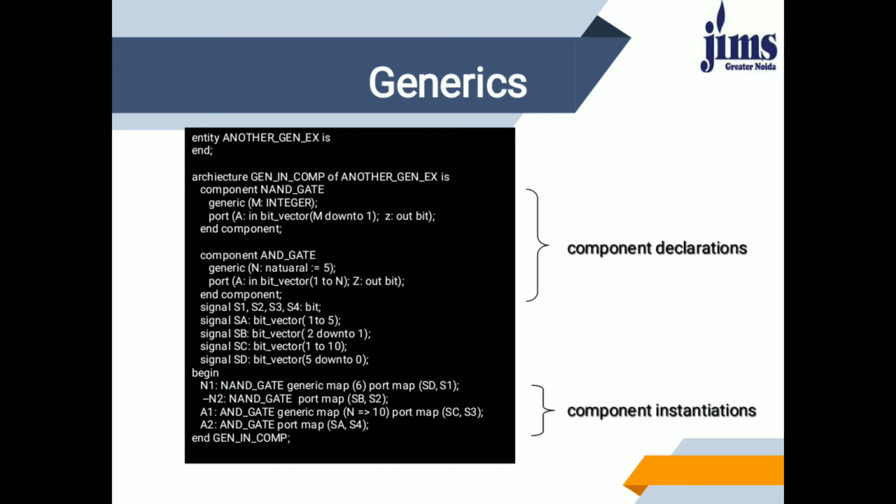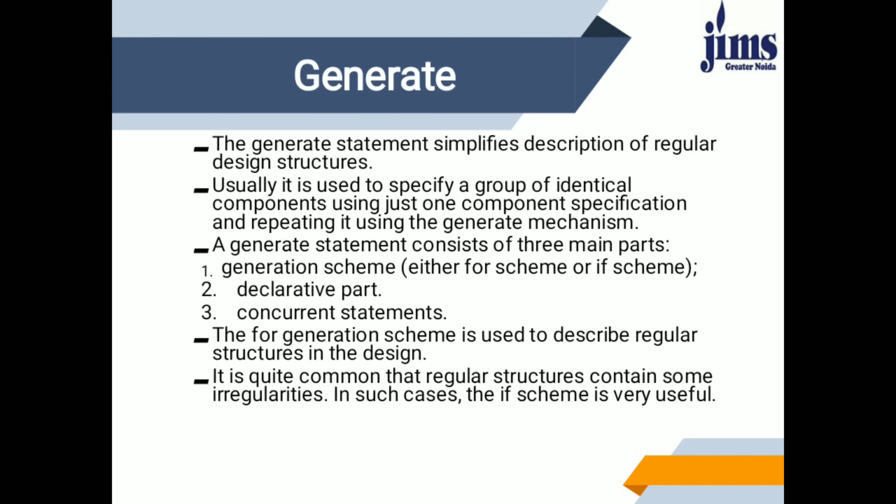Now we will move to the generate part. The generate statement simplifies the description of regular design structure. Generate is a concurrent statement that is used for conditional and repetitive structures during the elaboration phase of simulation.